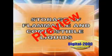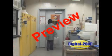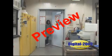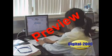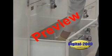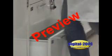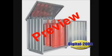Storage of flammable and combustible liquids. Storage must not limit the use of exits, stairways, or areas normally used for the safe egress of people in office occupancies. Storage is prohibited except that which is required for maintenance and operation of equipment. Storage must be in closed metal containers inside a storage cabinet or safety cans, or an inside storage room.